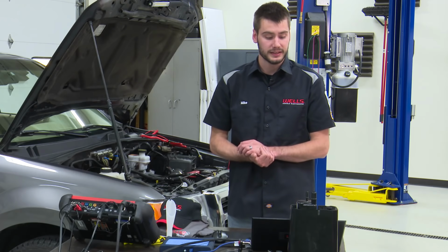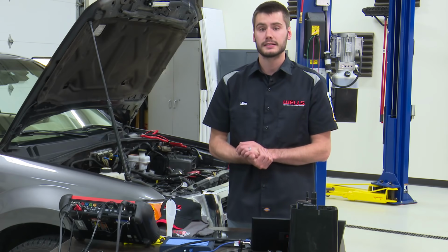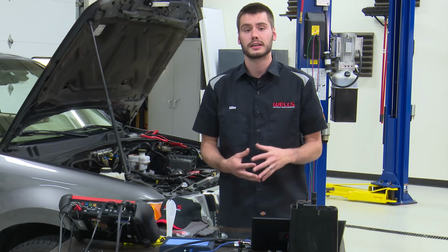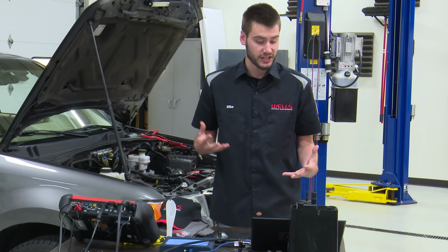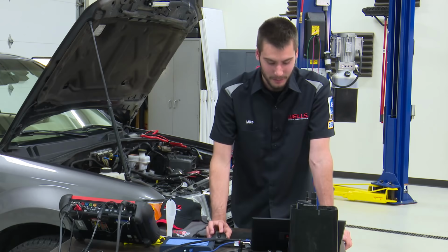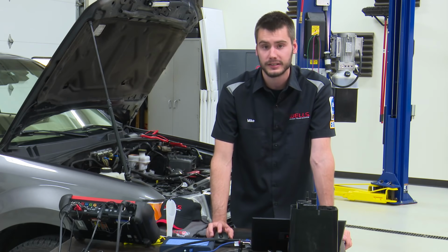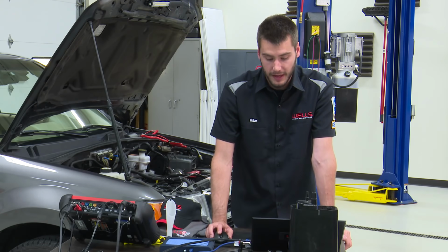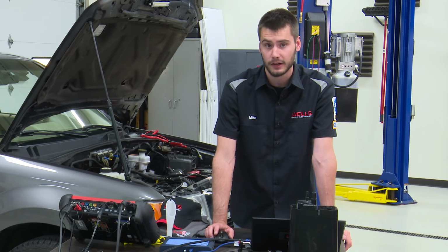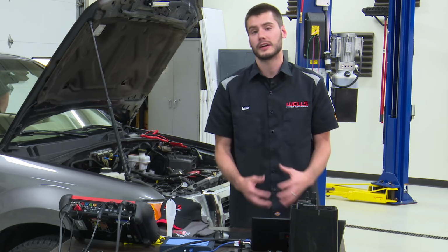The problem with this is that since our vehicles are now running ORVR systems, those vacuums are just sucking fresh air and whatever is in the air that day, and putting that down into the tank. Now I've heard that those vacuums can actually build enough pressure inside of the tank that it opens a relief valve on those tanks and lets fuel vapors out that way.